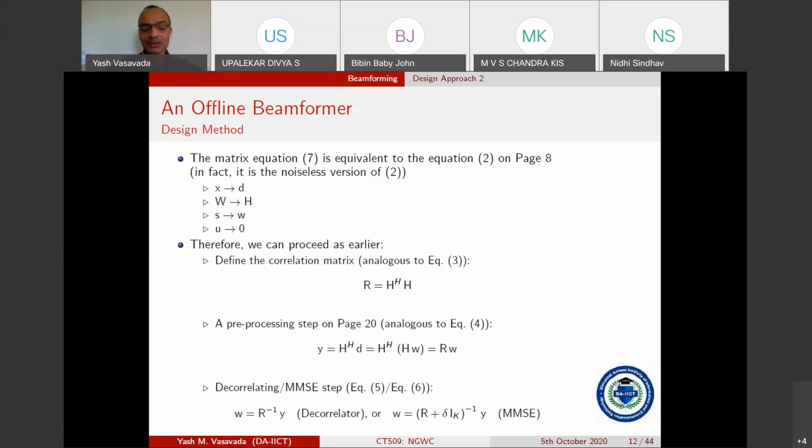And now, instead of coming up with the symbol estimates at the output of the beamformer, we are actually now defining the coefficients of the beamformer that will give us the desired suppression of interference in specific directions, and otherwise it will give us good beamforming gain in the direction that the signal of interest is coming from.